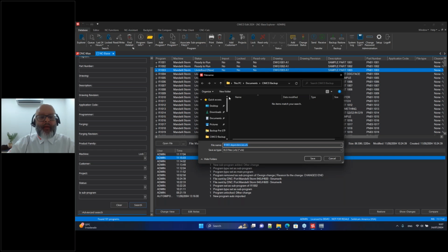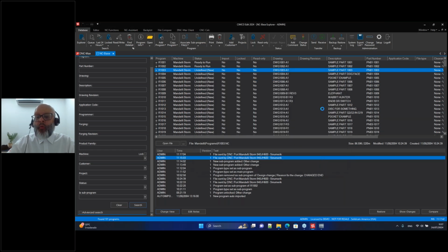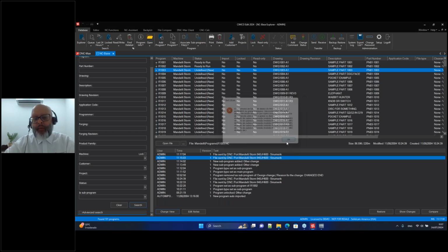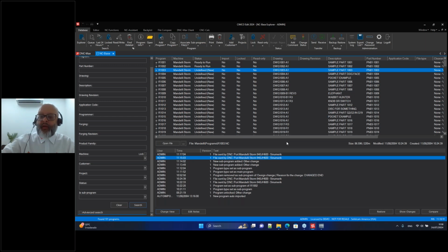Let's say, for example, that you need to change a tool, like Sandvik basically said, "Hey, I have a better insert or a better grade for you." And you should replace this insert in all tools and all programs that are calling this tool or using this insert. You can pull a report here, check all subprograms and main programs that are using a given tool, and then you can make a mass change and replace the insert, because the database tracks all the dependencies that exist between these files.